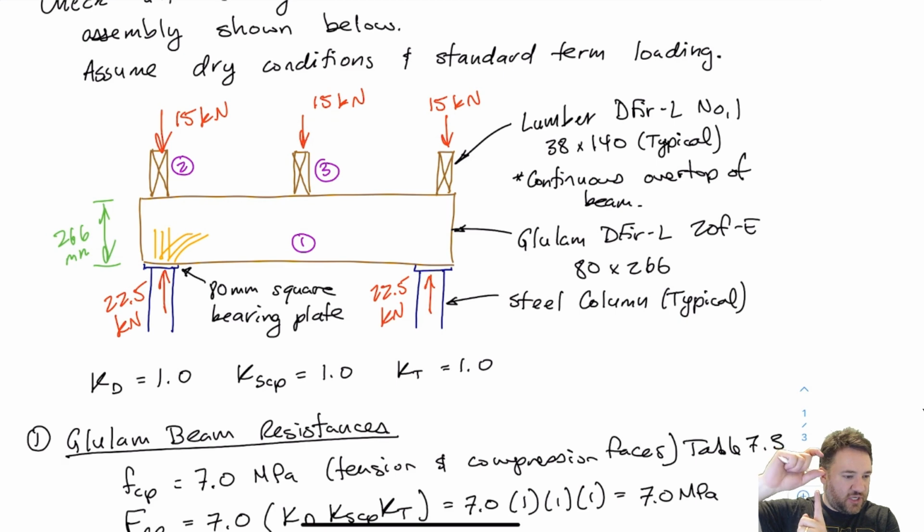So instead of just being near the surface of the beam and then eventually being transferred to shear to move elsewhere to get to supports, here it goes directly all the way through the beam, which means we have a longer length to strain, which means that for a given force, we're going to have a larger total deformation. So given force, same stress, same strain, but since we have a longer length, we have more deformation. And you recall from the other video that compression perpendicular strength design in wood is actually a deflection criteria, kind of reformulated into a strength criteria.